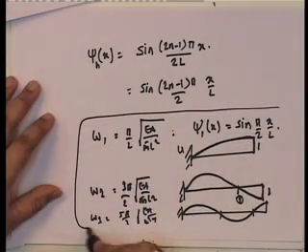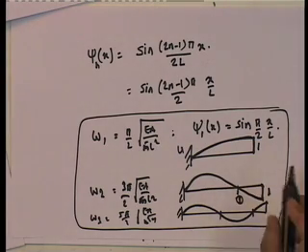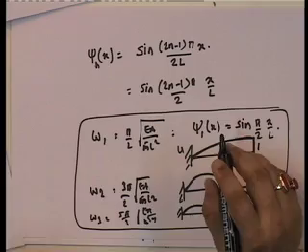This is a factor that you have to notice, that if you are looking at a particular situation, the first mode, no node. Node is where there are no displacements. Second mode, one node. Third mode, two nodes. Fourth mode, three nodes. This is how it goes. And this is the free vibration analysis. And we have got the mode shape. Only thing is that we have got the exact mode shape, because we have solved the partial differential equation in this particular case. Okay. So, now, this is for the axial vibration.